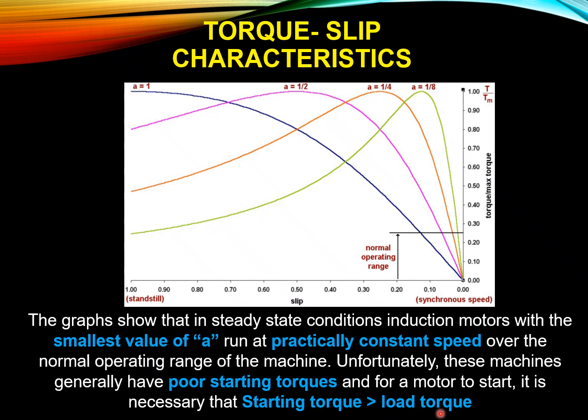Your load torque is what you attach, something that carries a weight, so you need to consider that as a load torque. If your starting torque is not more than the load torque, the motor cannot rotate. So it's necessary for a motor to have a starting torque more than the load torque.